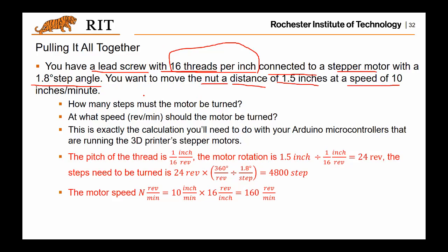Then there could be a few questions for you, right? The first thing is how many steps this motor needs to turn to travel 1.5 inch. So you have the distance, and for the pitch, that is one revolution. For one revolution, this screw will move along in this linear direction.